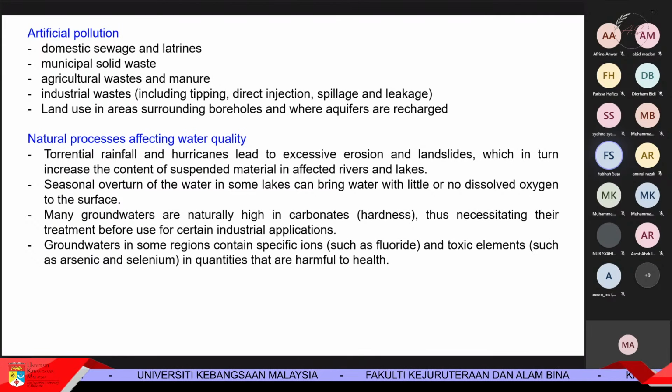When you spread on the surface, it looks very rapid, but after they enter the groundwater, it will be there for a very long time. So pollutants that are fully soluble in water and about the same density will spread through the aquifer at a rate related to the groundwater flow velocity. So if the flow velocity is very low, like with chloride contaminated water from sewage, it will be there for a long time.